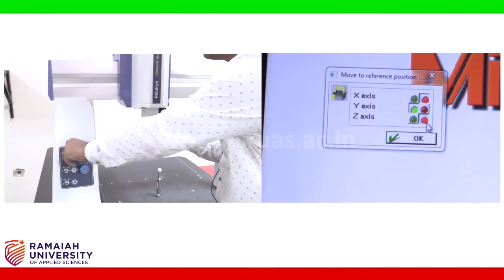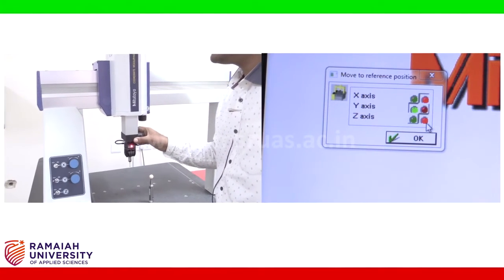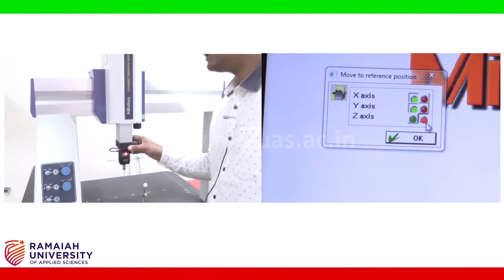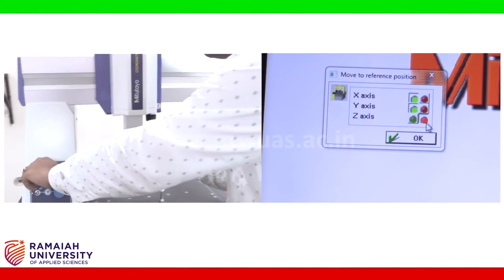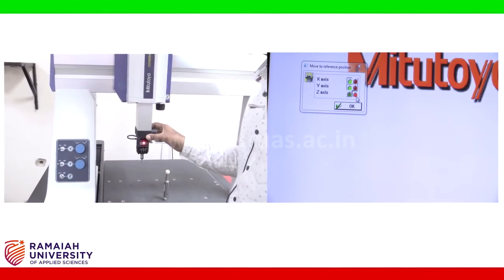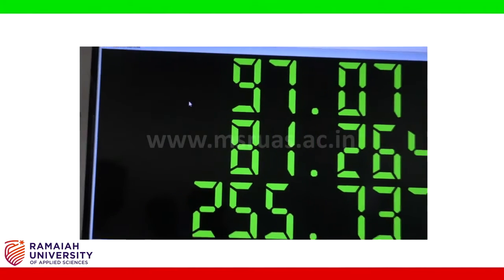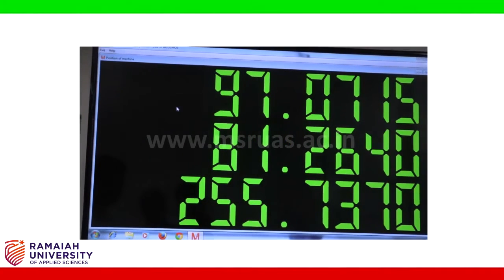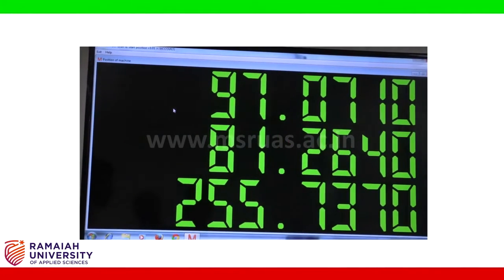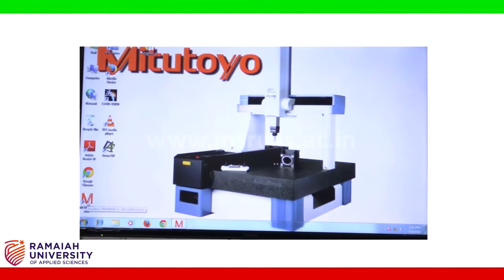The next is the x-axis. I am bringing the x-axis to the home position, and similarly you can see on the software the x-axis red pointer turning into green. The last is the z-axis, which I am moving to the home position. Now one can see the homing position, and these are the positions of the x, y and z axes. Now let us open the mCosmos software.